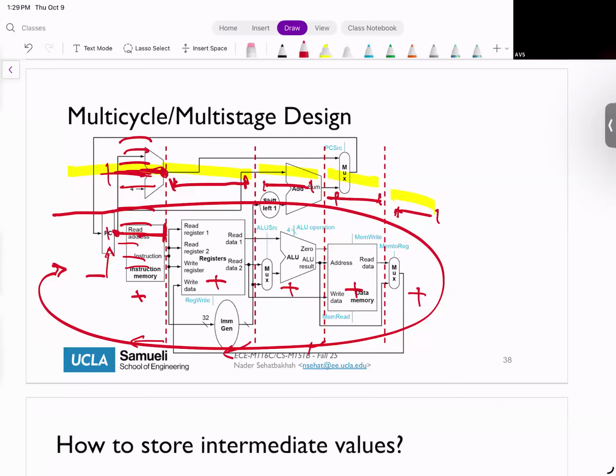Yeah. We only get a speed increase when we have a pipeline. But if I somehow can skip things, then I can also get a speed increase here, because remember I told you that the clock cycle was determined by the memory, but here the clock cycle is no longer determined by memory. It's determined by whatever the max of these stages is. So at best you can clock things 5 times faster.